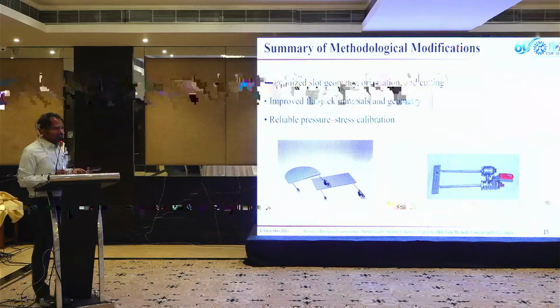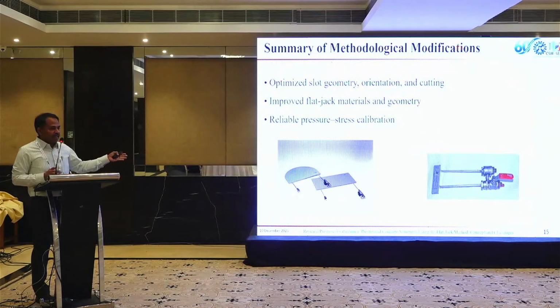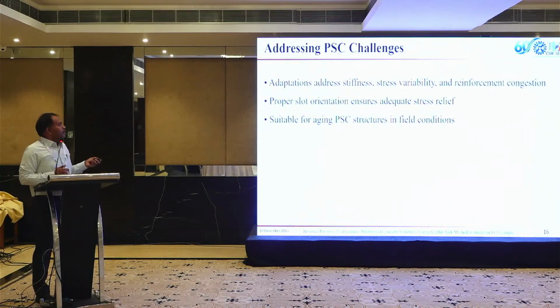concrete structure. So finally, the adopted modification: this is the conventional flat jack that is being used in masonry or rock mechanics, which has been transformed into a flat jack suiting the requirements of pre-stressed concrete structures. So we address the challenges by modifying the size and shape of the flat jack.